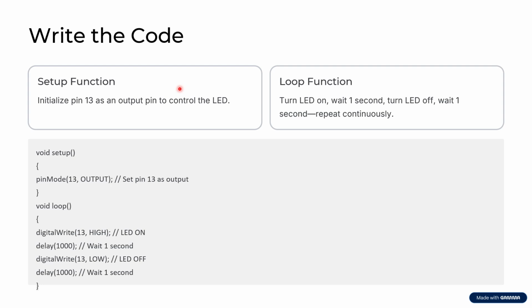In Arduino programs, we have 2 parts, the setup part and the loop part. The setup part runs once to prepare, whereas the loop part runs continuously until we come out of the loop. Here we are using pinMode and digitalWrite that make the LED blink.